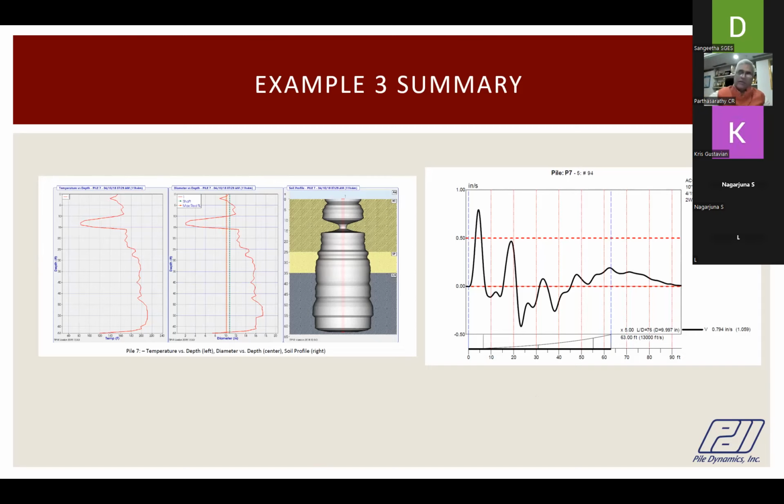So when they started excavating to the basement, after 3 meters, 4 meters, they could see the top of some piles. They were puzzled and surprised because their elevation of the top of pile is minus 6 meters, but at 3 meters, they could see that the concrete is overgrown. They finally confirmed this when they did multiple PIT tests. And you see the bottom 3 meters probably is very defective. There's a collapse of the borehole, and therefore you see the pile going up.